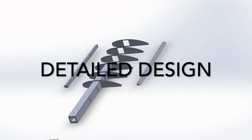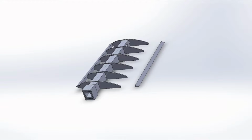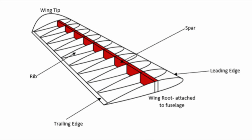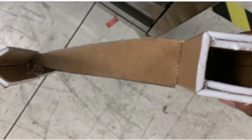We used SolidWorks to make the 3D model of the wing. It was required to make an assembly of the foam board wing consisting of the spar, ribs, trailing and leading edge components. We assumed the load of the aircraft was to be supported by the spar only, therefore the only constraint faced with the design of the secondary structure was ensuring the size of the spar fit into the geometry of the wing provided in the brief.